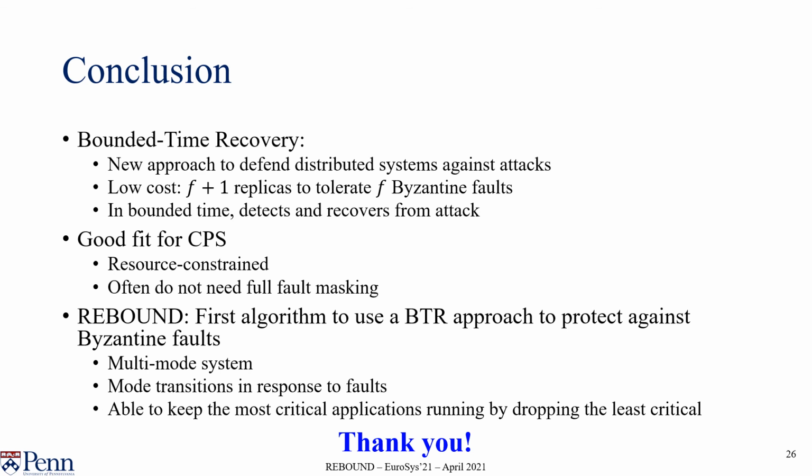REBOUND is the first concrete algorithm to use a BTR approach to protect against Byzantine faults. It uses a multi-mode system so that when a fault occurs, the set of nodes in the system can transition between modes in response to the fault. By doing so, REBOUND is able to keep the most critical applications running because it can migrate the tasks of the critical applications to healthy nodes, in the process perhaps dropping the least critical ones.